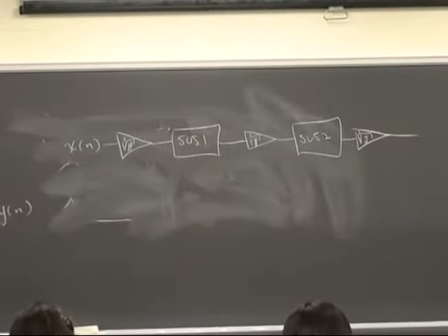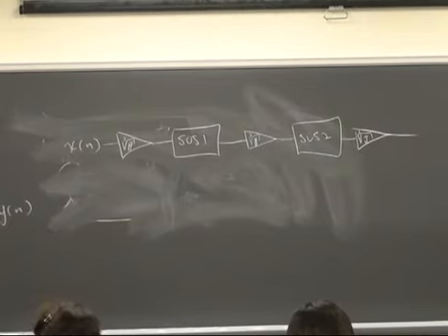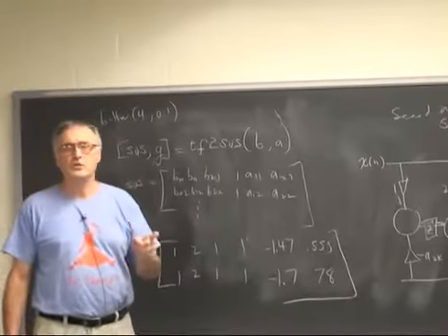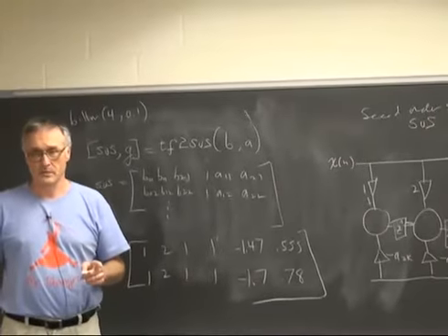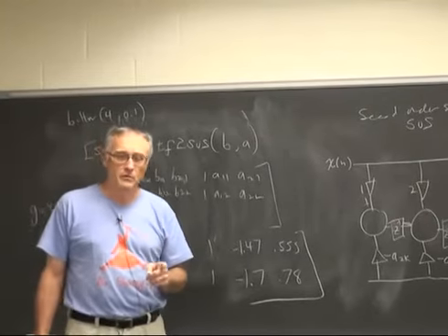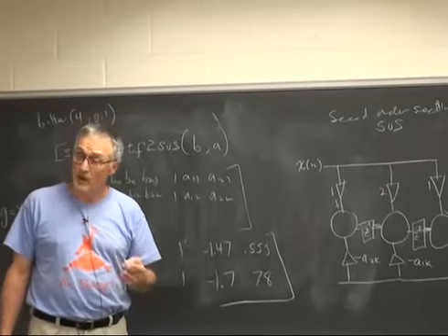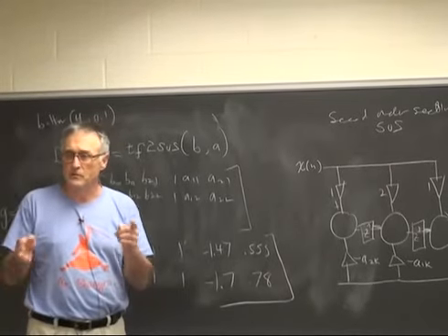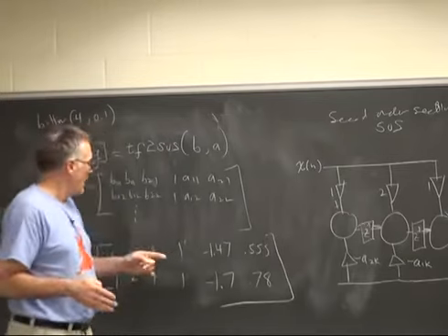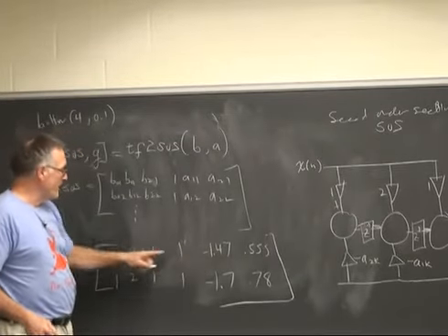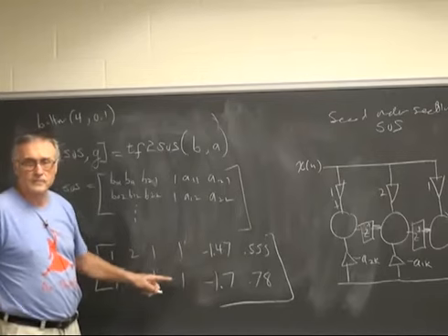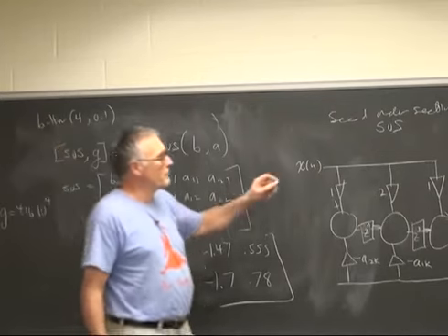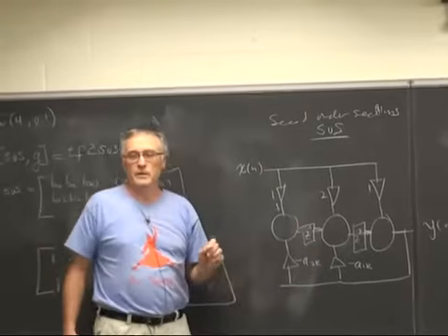I have to tell you though, second order section arithmetic works best in floating point, because now multiplying by a constant costs you nothing in terms of accuracy, because all of the accuracy you lose in a floating point operation comes in the subtracts, right? Subtraction of numbers that are almost identical. And we've optimized that by making all of these numbers about the same size. So second order sections work best if you have floating point arithmetic available.